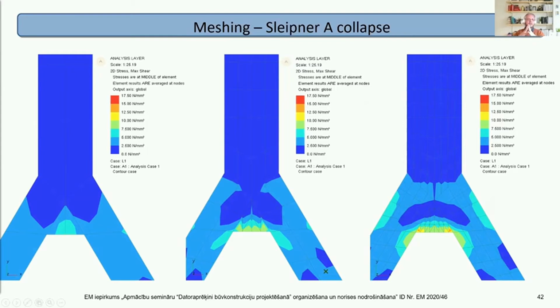Where non-linear models become sensitive is they're much more sensitive to differences in stiffnesses. So with a linear analysis, you can have some quite large and quite small elements, and it still functions quite well. Non-linear models tend to be much more sensitive to stiffness ranges. So you've got to have elements closer together in stiffness. So, for example, doing a non-linear model, I might have some quite large elements, which therefore have quite low stiffness, and it gives problems. I subdivide those ones so they give similar stiffness to other parts of the model, and that can improve the analysis convergence.